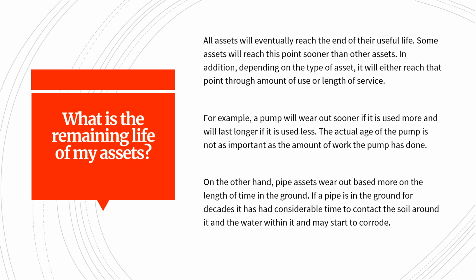Cast iron pipe may last 100 years at one facility and 30 years at another. It is best to make judgments of asset life based on past experience, system knowledge, existing and future conditions, prior and future operation and maintenance, and similar factors in determining useful life. In the absence of any better information, a system can use standard default values as a starting point. However, over time, the system should use its own experiences to refine the useful lives.